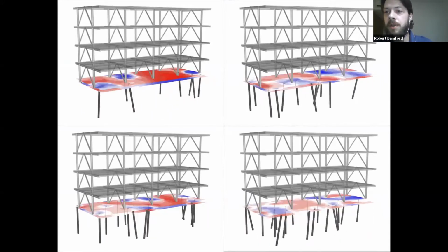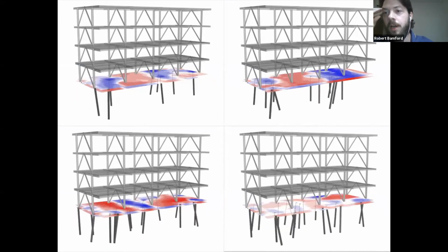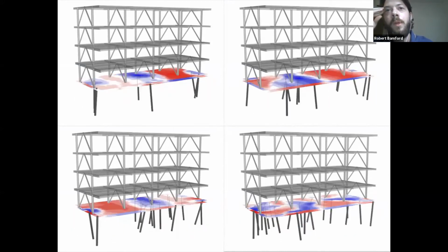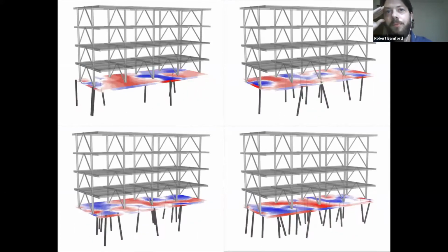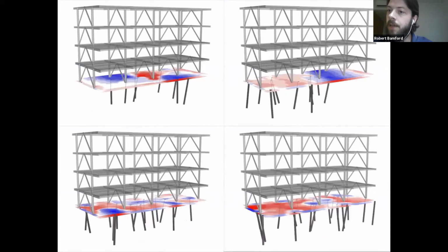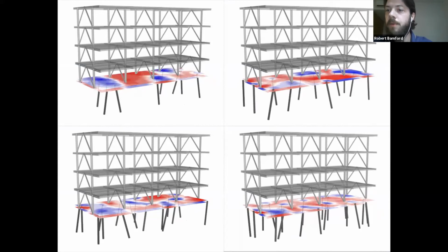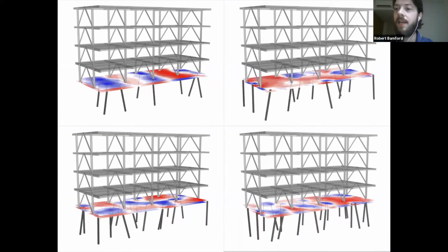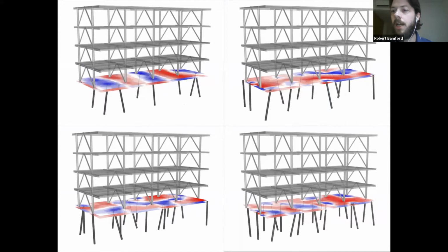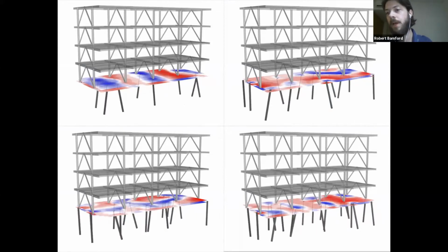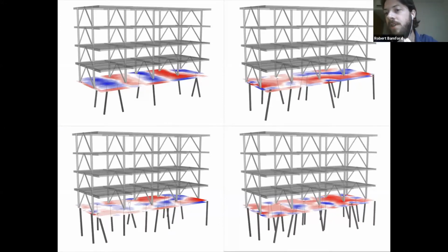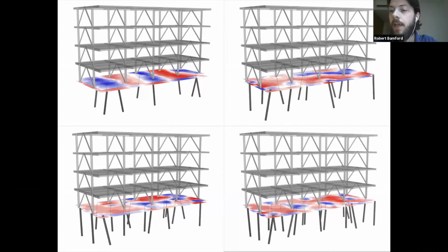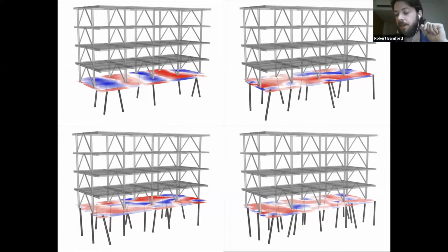And this is using a multi-stage geometric optimization approach. And the same scenario is true here: given the specific elements the freedom to move around, we find that things very rarely want to be straight. They actually like to incline slightly. And so when things are being analyzed under load combinations, including lateral loads, it's very advantageous to have slight inclines that resolve globally, but can resist lateral loads directly through direct strut action.